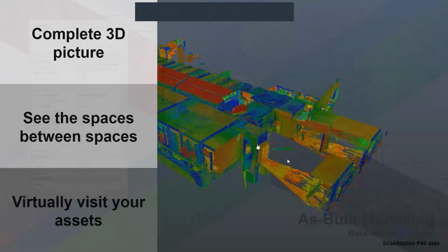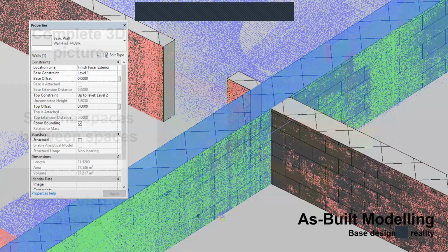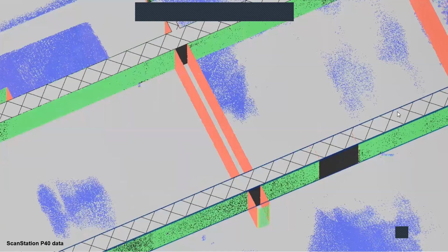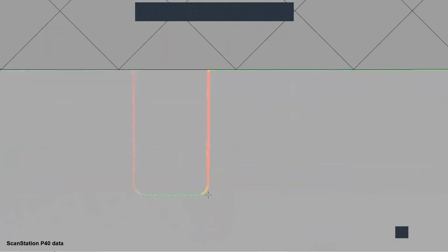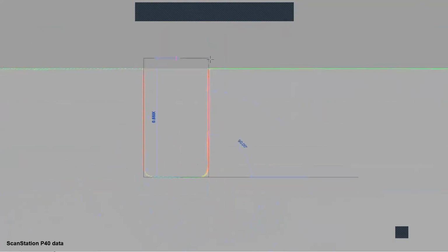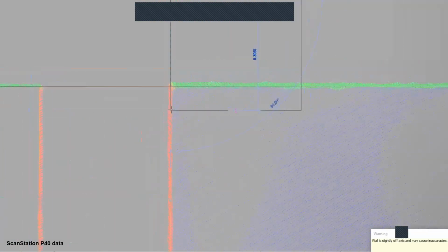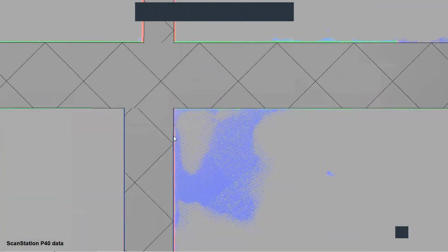Post that, this is an example which shows how we can do BIM modeling. This is what we are working on in Revit. In between, what we did is we loaded a point cloud, which we captured from the field. These orange lines, you see, are basically the point cloud which we captured, and now we are tracing the point clouds using the CAD tools or Revit tools together, and then we can do as-built modeling for the walls, for the ceilings, for all the areas of the building at no hassle.